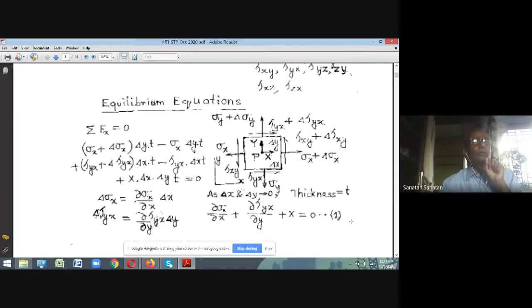When you are trying to find out what the forces in the grinding wheel are when it is rotating, you don't have any other forces but the centrifugal forces. So in that case, you don't have any external load acting other than these centrifugal forces. So if you want to analyze the grinding wheel when it is rotating, you have to bring in these body forces, which are indicated as volumetric forces.